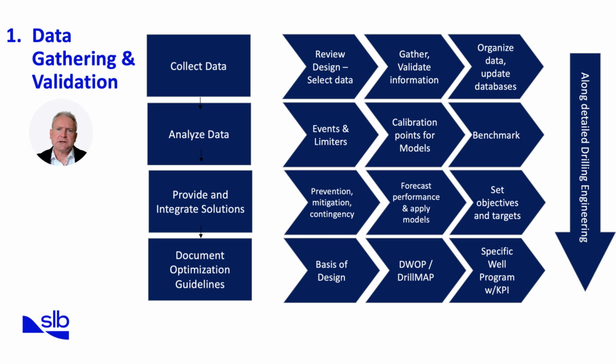The second stage is analyze data. Here we focus on learning from the past. Events and limiters from offset wells are reviewed to identify risks such as stuck pipe, lost circulation, or performance bottlenecks. Calibration points are then applied to tune engineering models, ensuring they accurately represent the field reality. Benchmarking is also carried out, comparing our performance against industry or regional standards. From this analysis, realistic performance targets can be set.